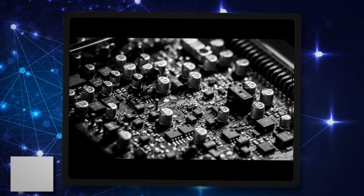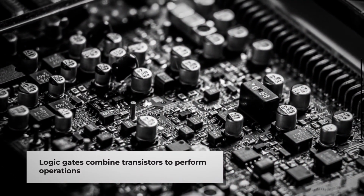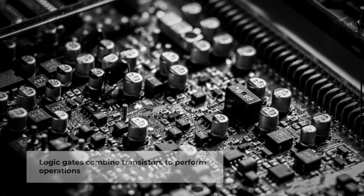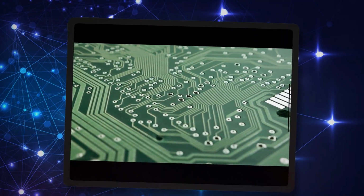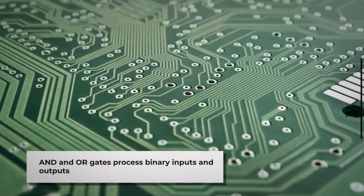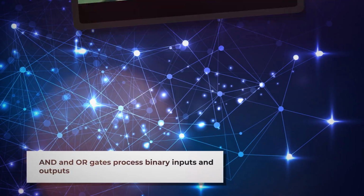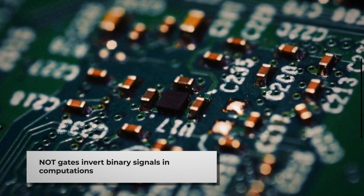Individual transistors become useful when combined into structures called logic gates. A logic gate takes one or more binary inputs and produces a binary output according to a specific rule. An AND gate outputs 1 only if both its inputs are 1. An OR gate outputs 1 if either input is 1. A NOT gate simply flips its input, turning 1 into 0 and 0 into 1.